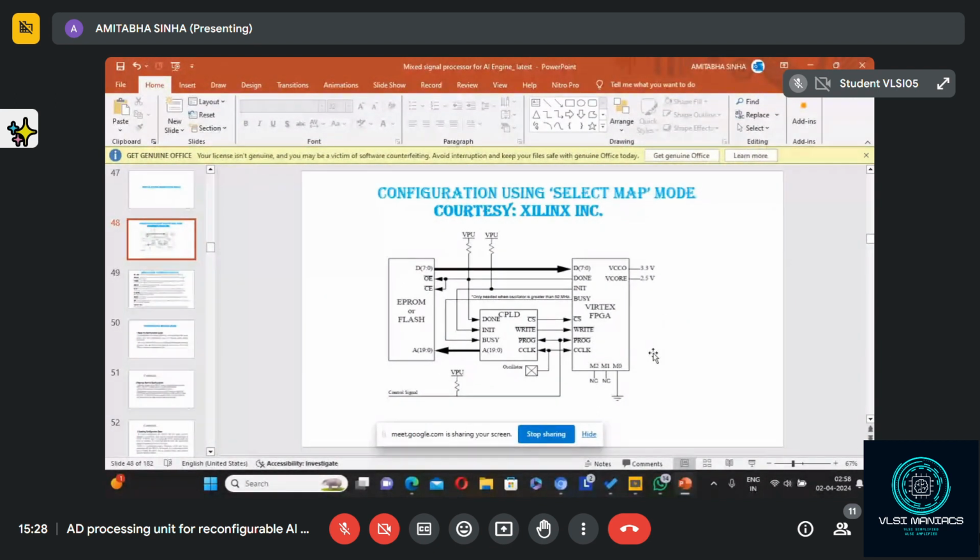First it needs to be programmed. Programmed means it needs to be configured. So different kinds of terms are used. Normally, in the industry, we mostly use the term configuration. So unless the FPGA is programmed, it cannot do any work. This programming task will be done by this CPLD. It will create the environment such that the bit streams, in the form of bytes, will be downloaded from the flash memory to the FPGA one by one.